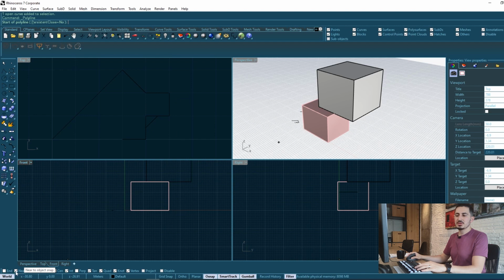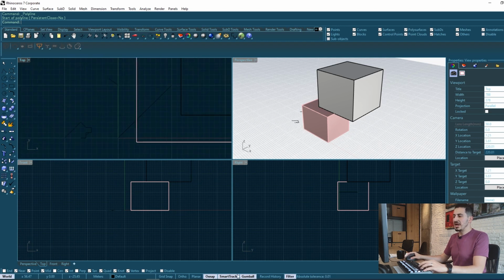I prefer not choosing the near point, which is if you want to create some points on the line itself, because sometimes it affects your accuracy if you want to choose one point in the middle. If you have the near option turned on, then it might get a bit inaccurate and create a near point that is different from the one that you want to choose. But it's your choice. After using and having some experience with these, you can choose the best for your work. What else we have?